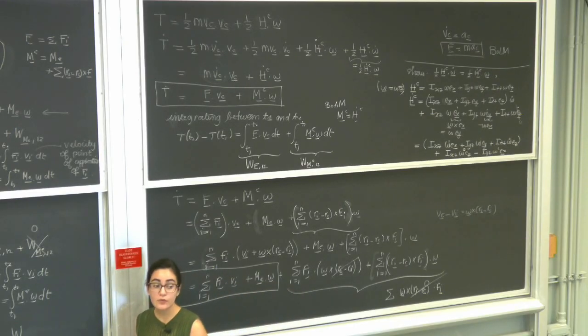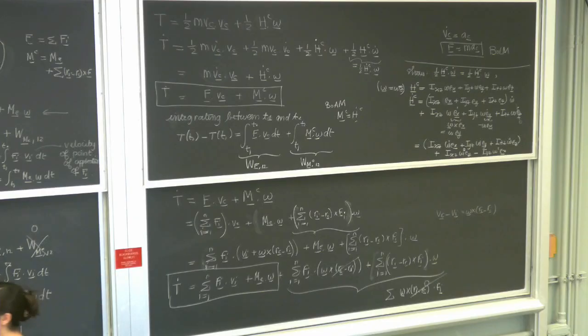It's 0, because it's not moving. The work of the reaction force at O is the integral of RO dot the velocity of which point? O, the point of application of RO. And the velocity of point O is 0. So we get that the change in potential and kinetic energies is equal to 0. Energy is conserved. Sounds good?